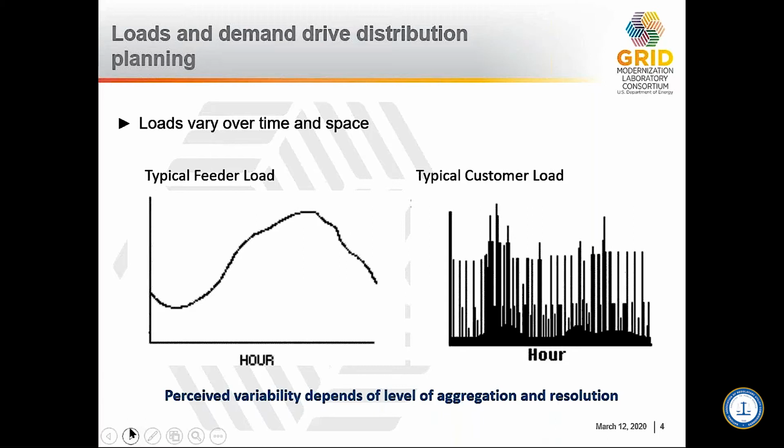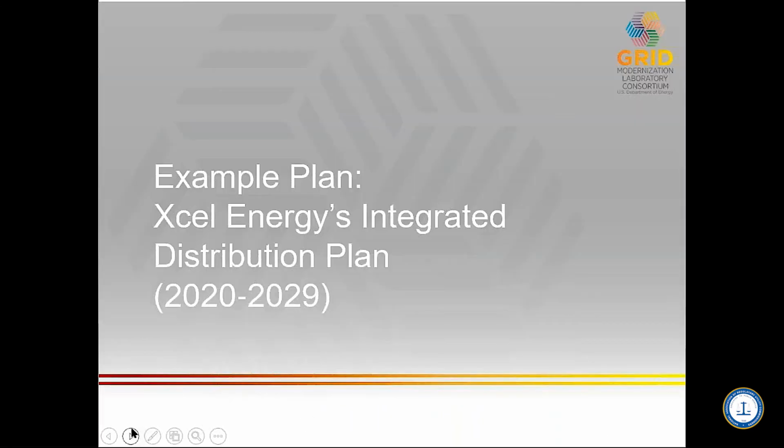In the morning, there's a minimum load. During the early morning time, the load is rising as economic activity takes place. It hits a peak sometime in the late afternoon, and then it declines until the nighttime activity is done, back to the minimum load. This is fairly typical of load that's aggregated at a higher level, such as at the feeder and the power transformer, the bulk power system.